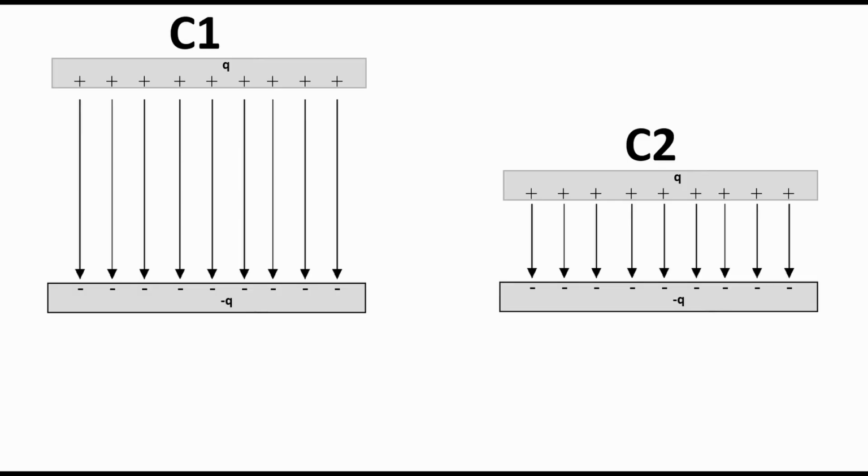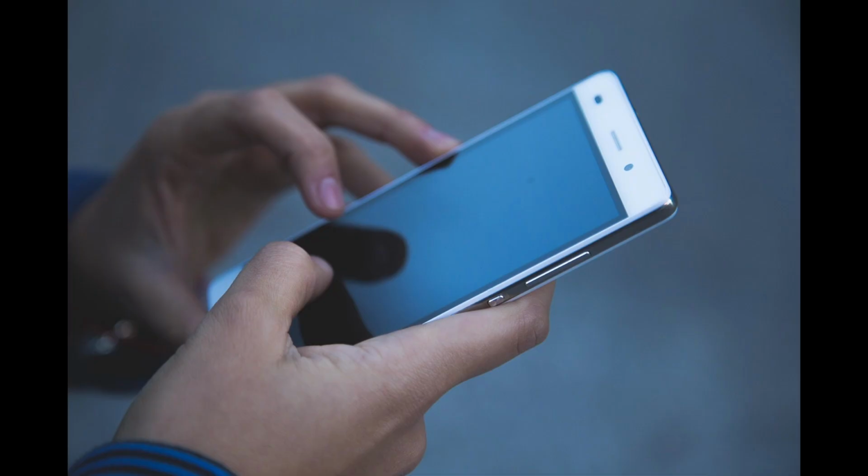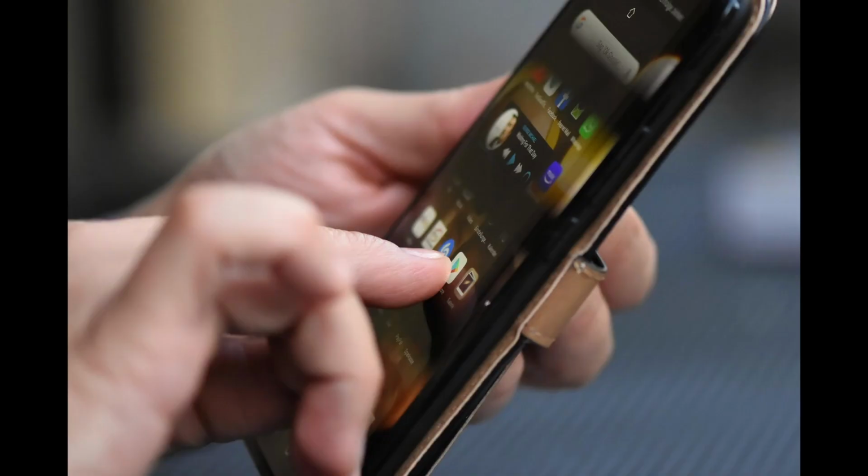Displacements that alter the physical dimensions of the capacitor will alter its capacitance value that can be detected in a circuit. For example, applying pressure to a plate can reduce its plate separation, or a shearing of the plates will change the plate alignment, all of which can be detected. Modern cell phones and touchscreen devices also use capacitive sensors to detect touch. However, in these cases, pressure doesn't need to be applied, and instead, human skin acts to disrupt the capacitor's electric field, which can be detected.